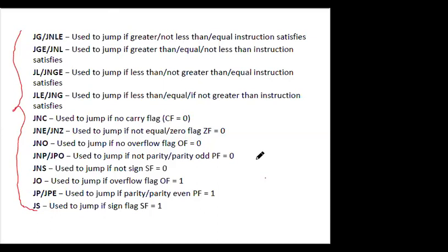So depending upon the flag register, we had instruction sets in 8085, where we had only an 8-bit flag register and 5 of the flags were active. But in the case of the 8086 microprocessor, we have a 16-bit flag register, and there are many more flags or status bits to be updated. So these instruction sets generally represent the status of the various flags, and depending upon the status of the various flags, these instructions have been modified in 8086.